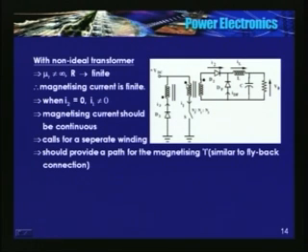The dot is connected to the positive of the battery, positive to cathode, anode is grounded, so D3 is reverse biased. No current can flow in this direction, or in other words, no current can leave the dot in the tertiary winding.